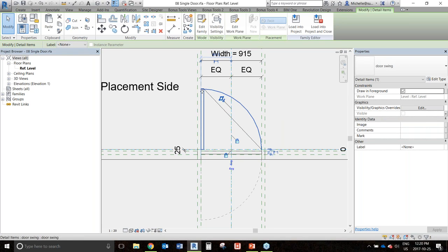And that gets to be really difficult and complicated to just use line work to control all of that. So when you have a certain set of objects or lines within a family that it's getting really hard to control all of them, but they're kind of grouped together, this is why you would nest something in. So we nested the door swing in that already has the swing capability so that you can control that and not have it mess up the family. It's just a simpler way to work.